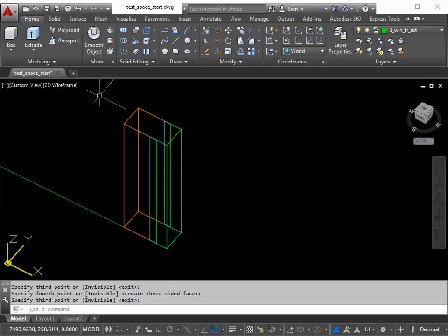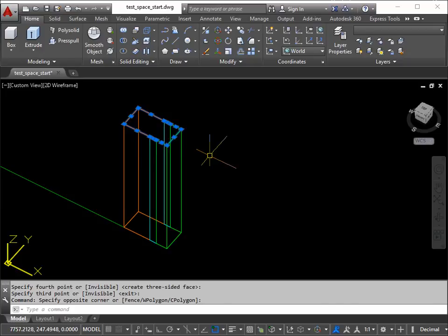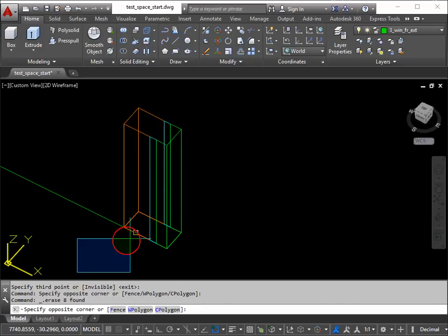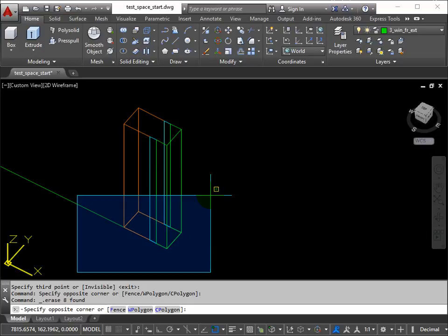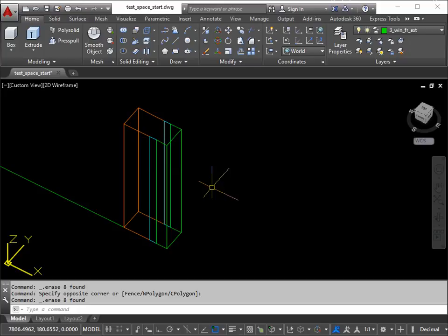The two objects that we used to help us draw this aren't needed anymore, so I can erase them. They're a bit tricky to select, so be careful and use a blue selection window, and it should only pick the objects that are completely inside it. Press delete to remove them. Do the same at the bottom, so there's no command active. Blue selection, delete, they're gone. We don't want to clutter the drawing with lots of lines unnecessarily.